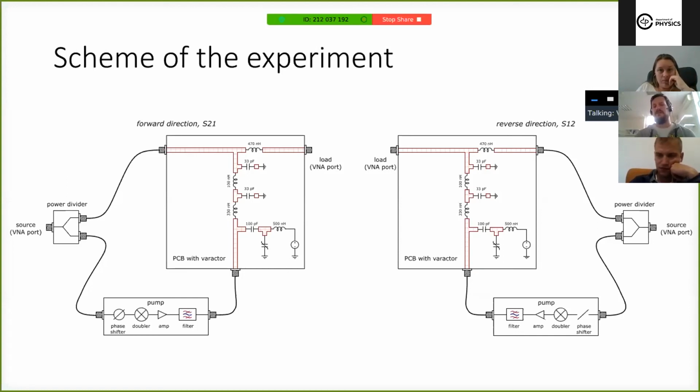For the varactor diode, the main limit is the resistance of the PN junction, because this is the fundamental limit which cannot be mitigated. But there are varactor diodes which are used in the range we plan to work on. In the 10-20 gigahertz range, I have seen in the literature that people use varactor diodes for parametric amplifiers. So I don't think there is a fundamental limitation, but of course, to fabricate anything in this range will be much more difficult due to various parasitics and the more precise manufacturing which we will need to use, and so on.